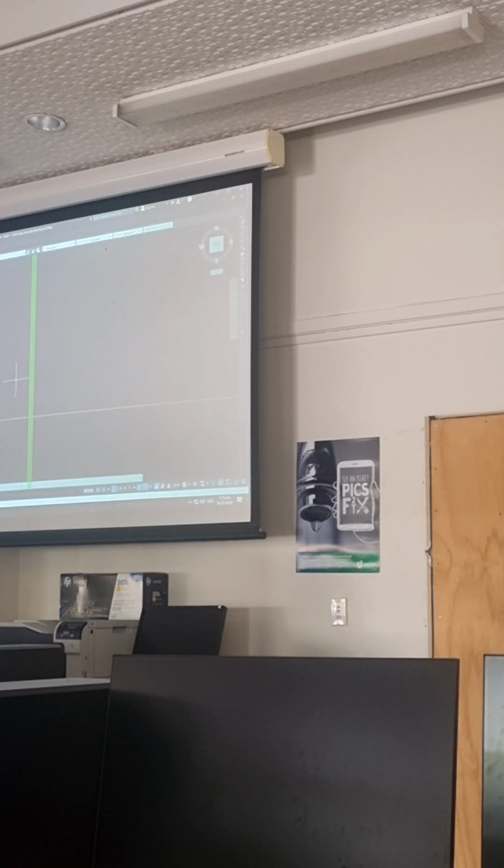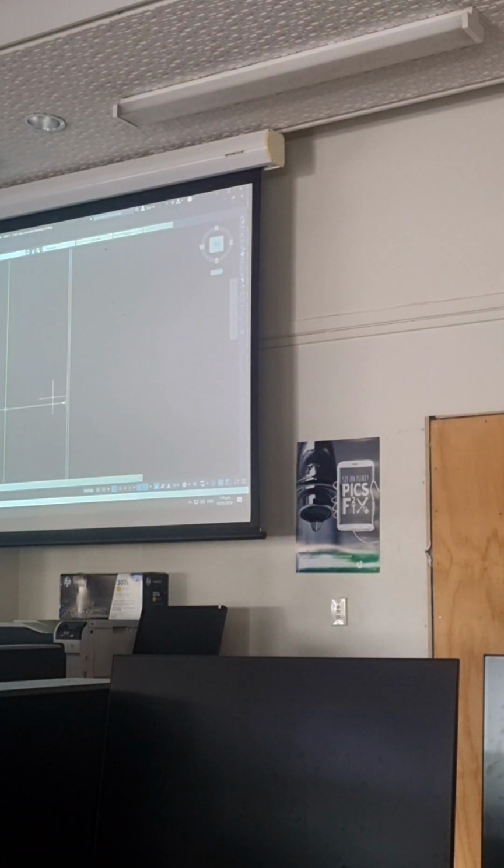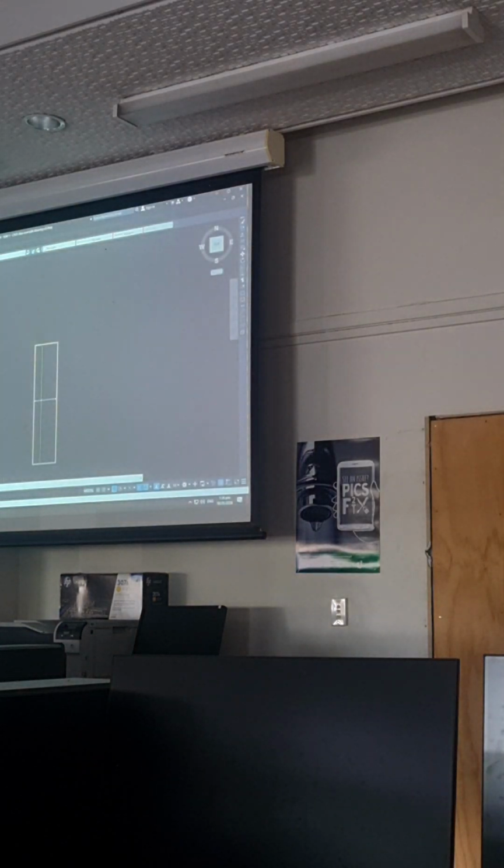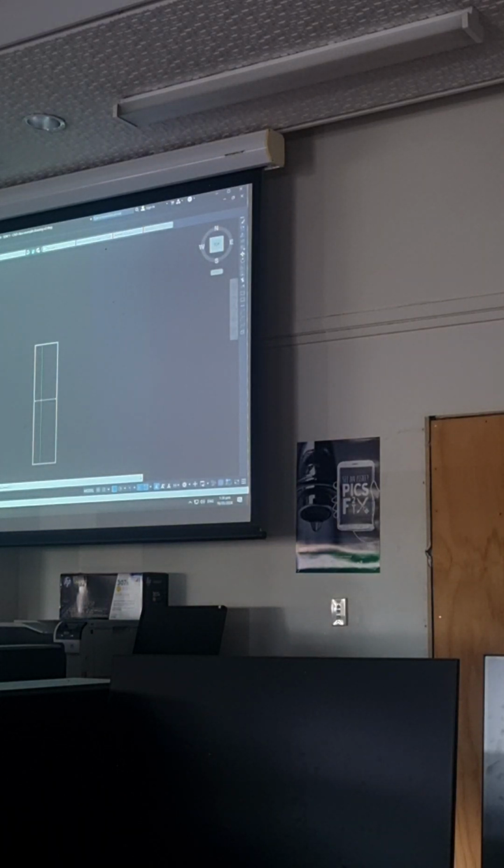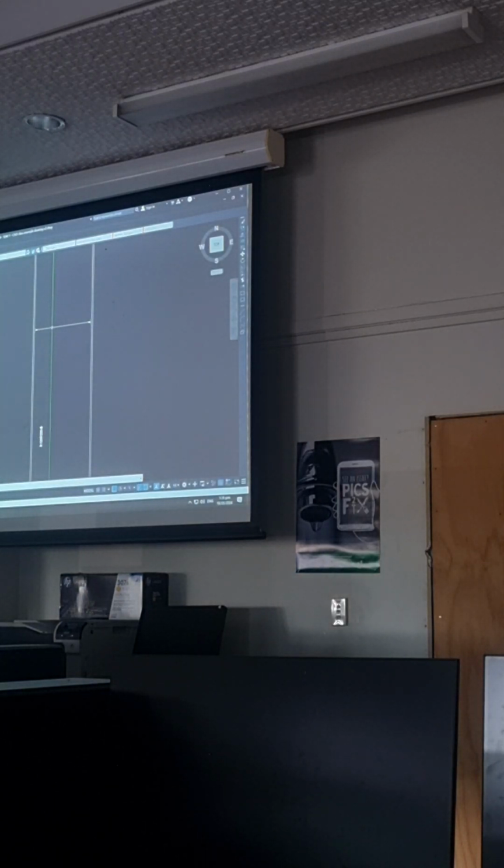Now the circle here will be from the intersection point there, and it's a 16mm bar, so why don't I make it 32? It's about right, and we're done. Okay. Delete that. The eliminator's in place. So all we need to do is put some text on here. Now the problem you're going to have is that you're going to have overlapping bars. So that creates its own little problem. Get into that in a minute.